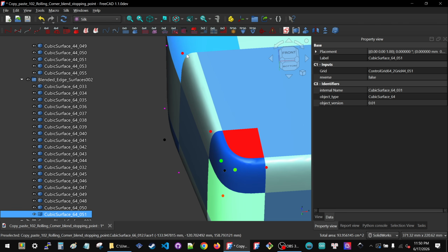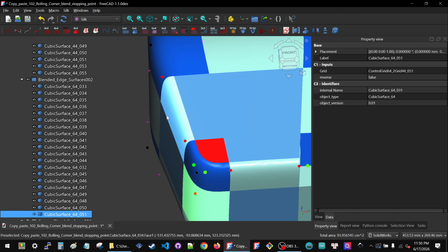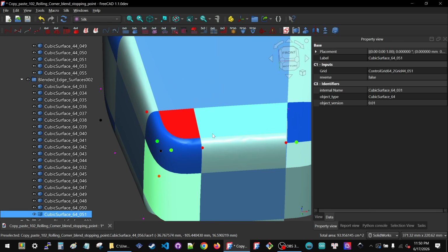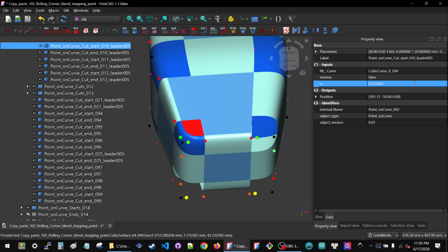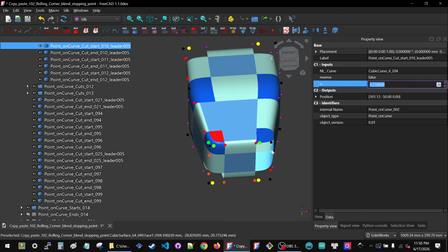This small fillet here rolls around this big one. And if I wanted to, like right now, this leg of the blend is pretty big, but it still gives the impression of a small fillet just in this area. I can also edit this point and bring it back up, but it won't have that much of an effect. It's already handling it. The difference in size on this piece is already handling the separation.